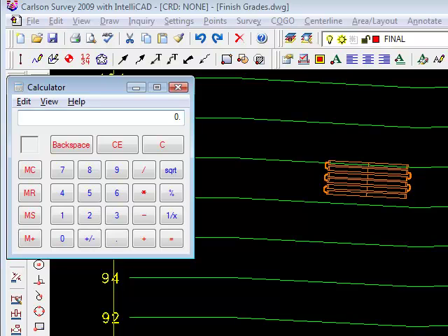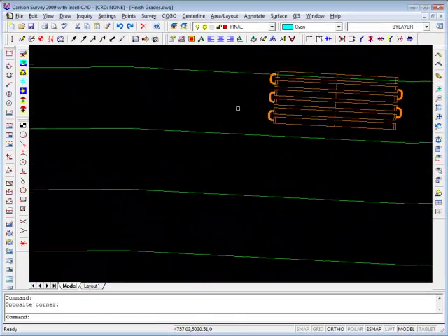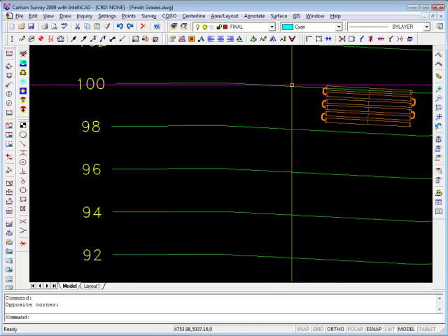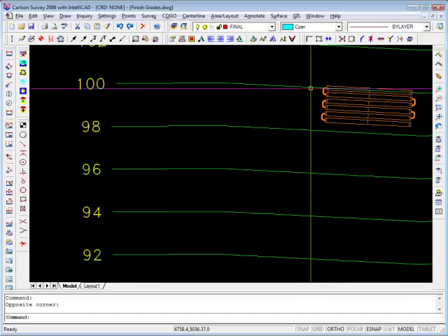You're wondering, how is that going to be useful to us? Well, let me demonstrate. This one's going to be a little easier because I purposely made nice, convenient numbers, but we want to determine the slope of the site and the field, because we're going to parallel the terrain in the area of the field.